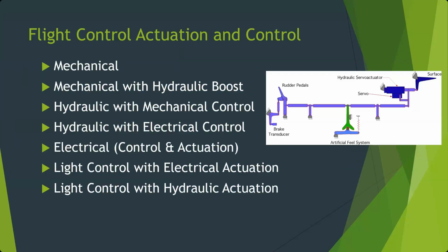And this is very similar. Mechanical with hydraulic boost is very similar to a lot of what most of you probably experience when you're driving your car with power steering. And then we go to hydraulic with mechanical control. So this is purely hydraulic operation with mechanical control. And at this stage, this is where hydraulics become extremely critical, because the mechanical control, all it's doing is moving a valve position. If there's no hydraulic pressure, then the flight controls won't move.